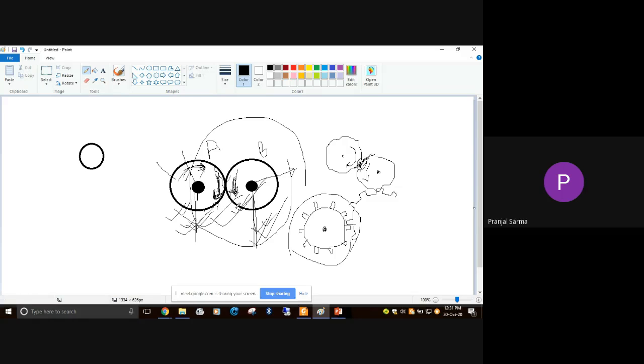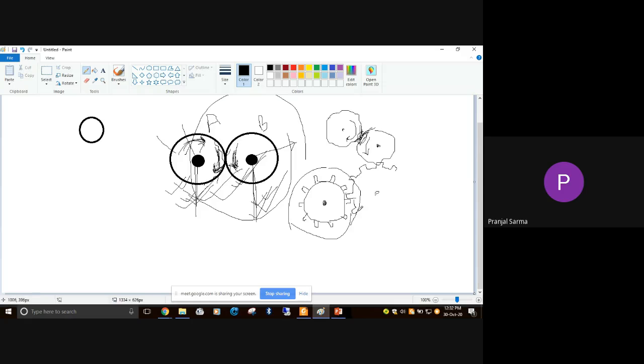and actually, sorry, it is not prime circle, it is pitch circle. With respect to that only, the contact and so on is defined. Suppose you consider this as the gear figure, gear A and gear B. In an actual case, if we're talking about a spur gear, the look will be somewhat like this one, not this one. But the contact is between the teeth, the teeth are in contact. That is how we can define them.